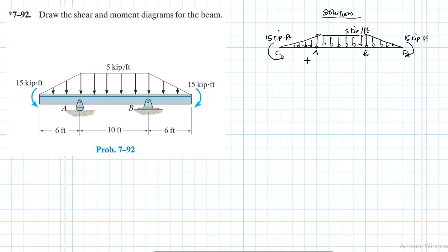Right, we have a reaction at A, which is going to be just a vertical reaction. Let me write A somewhere there, and also B, I move it a little bit further so I have space for writing. Alright, so there we go. I have AY there, that's a roller. I have here BY and BX.